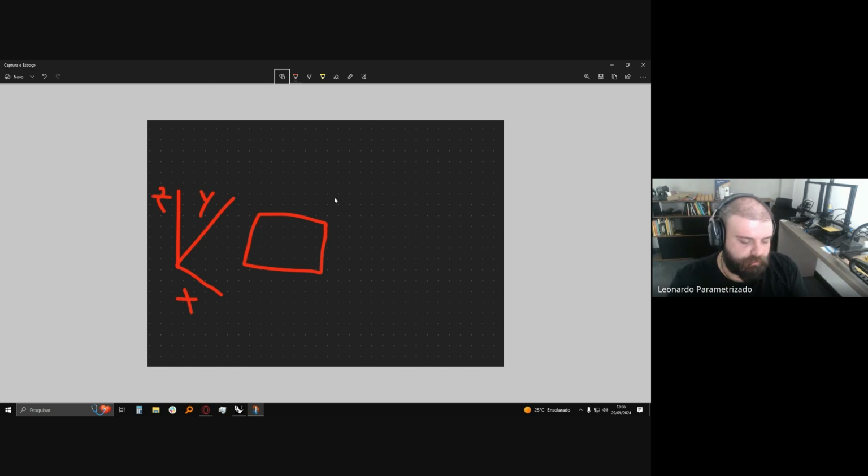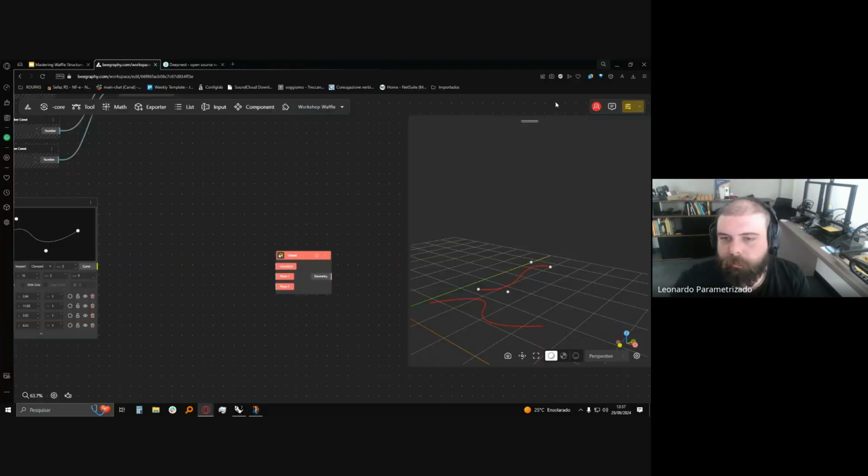I want to take this surface and put it in another orientation, in another plane, not necessarily in the planes from our axis. So the orient asks for a geometry, a base plane, which is this one in this case, and then we can orient it to another target plane. So I can get, for example, this surface here, and then I can orient it in this plane. For example, a plane such as this one, Z and Y, or something like this, okay?